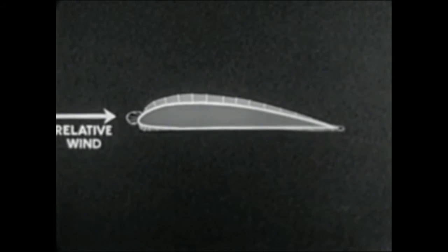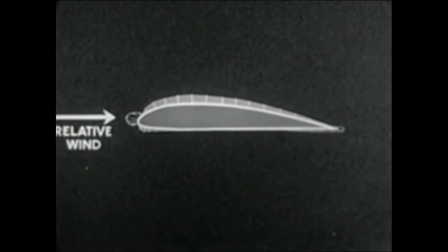At 0 degrees, there is a small bulb of positive pressure directly upon the leading edge of the wing. Another area of positive pressure encloses the trailing edge and extends forward about 1/4 chord length along the lower surface. Elsewhere, the pressures are negative.